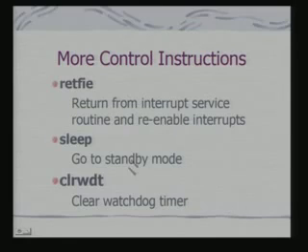There are some more interesting control instructions in PIC. This is the instruction RETFIE, or return from interrupt with interrupt enable. This is typically executed when you return from an interrupt service routine. Now, what is the difference between returning from an interrupt service routine and returning from a subroutine?